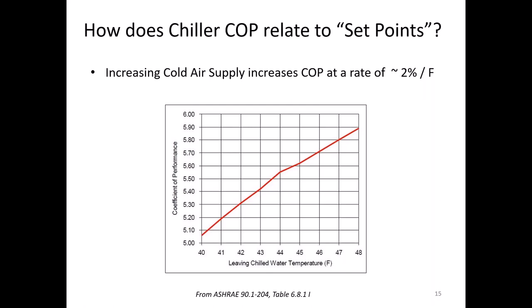And this is just what we were saying before about delta T. If the temperature coming out of the data center is high and your atmosphere is fixed, then the bigger that delta, the better the overall efficiency is, just again, due to the heat transfer equation. It's fairly straightforward, but it's powerful.